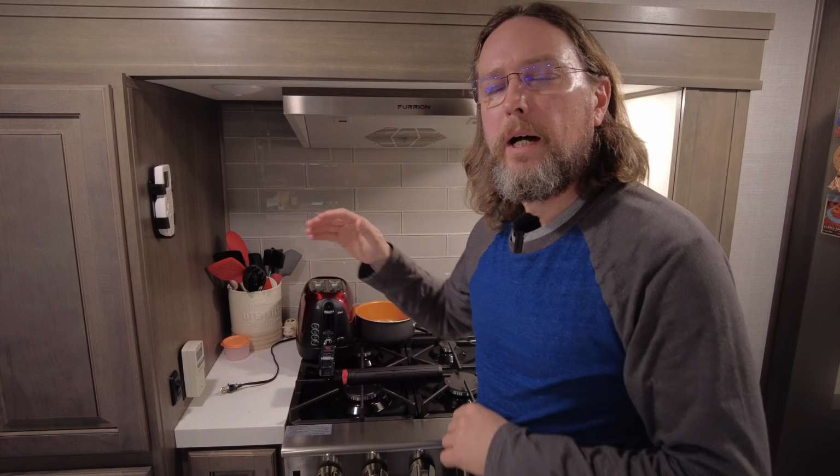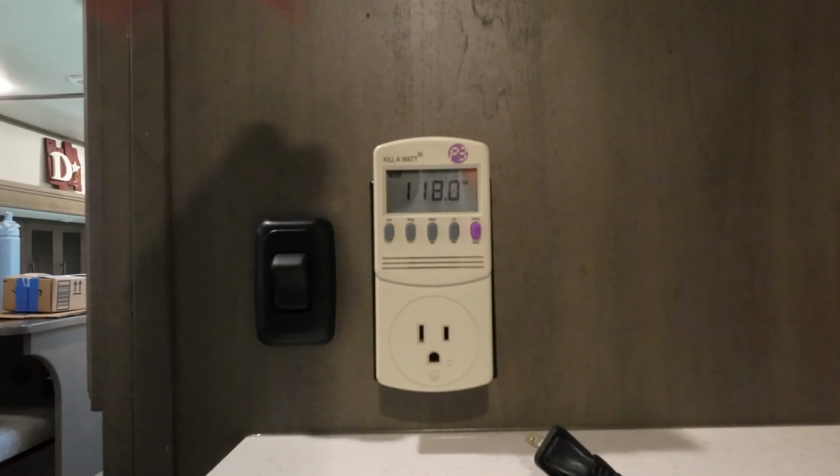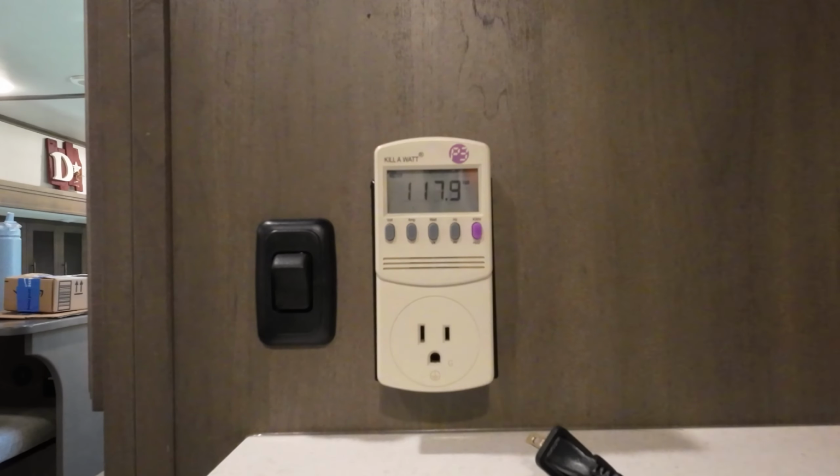All right, here we are over on the other side of the kitchen by the stove. This is where I've got my kilowatt meter plugged in now. When you first turn this thing on, it defaults to tell you what the voltage is at that outlet. As you can see here, we're reading about 118 volts. It may vary depending on what's going on with the whole system. I'm not gonna go into all the different functions that this thing does, because I really just wanna show you how it works when you're doing a power audit.